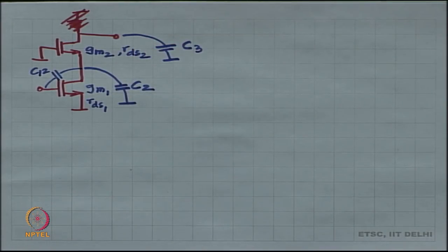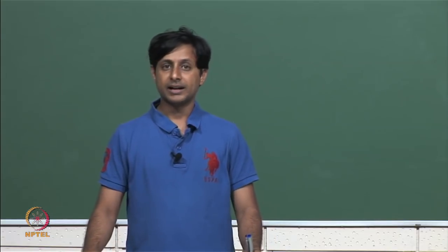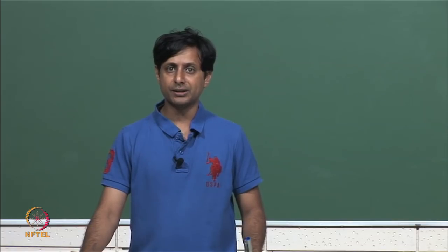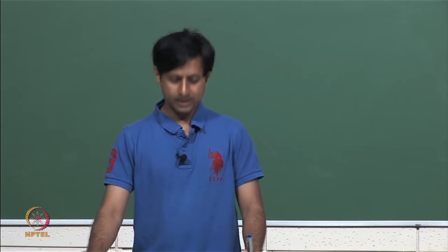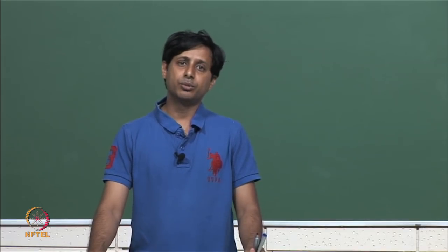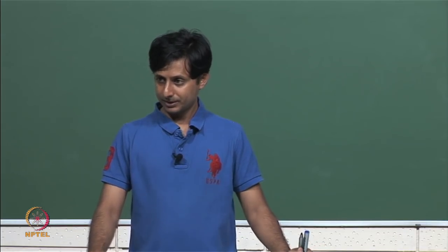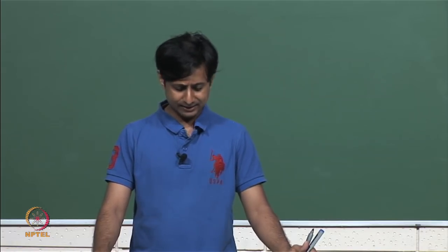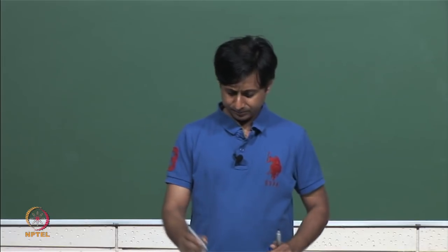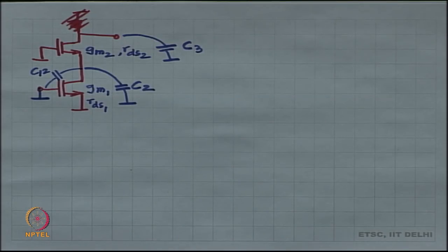This was our system that we had analyzed earlier, and when we did the analysis we found that the system has some zeros, and the zeros are going to be computed straight from the short circuit transconductance. This system has a couple of poles, and the poles are going to be computed straight from the output impedance. Then we had done an analysis of the output impedance of the circuit, and it is not very hard, because this is going to be at ground. So, C2 and C12 will appear together, and then it is just an application of one of our old formulae.